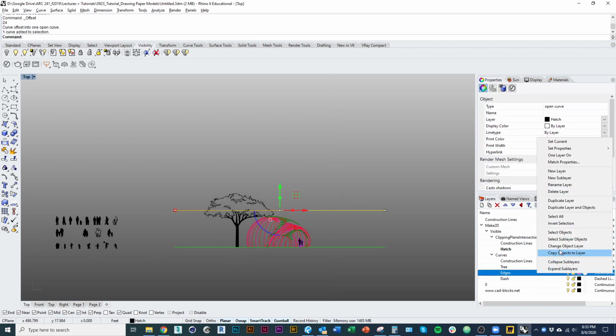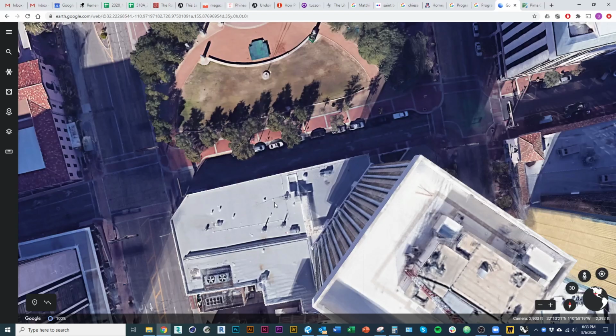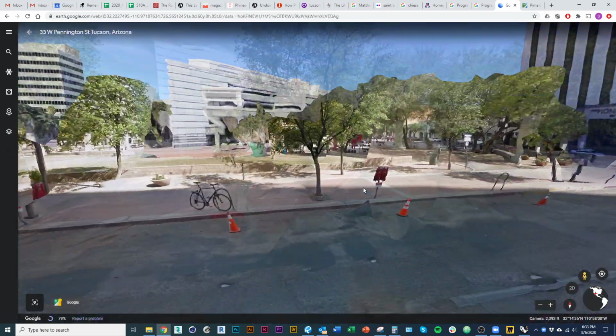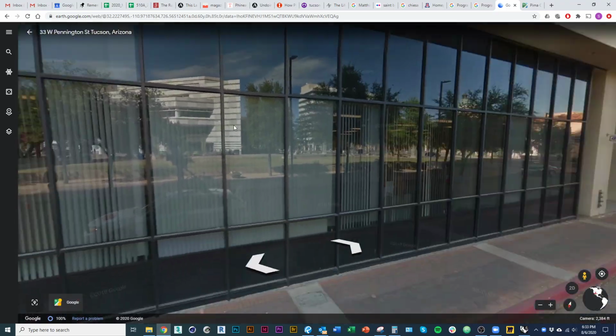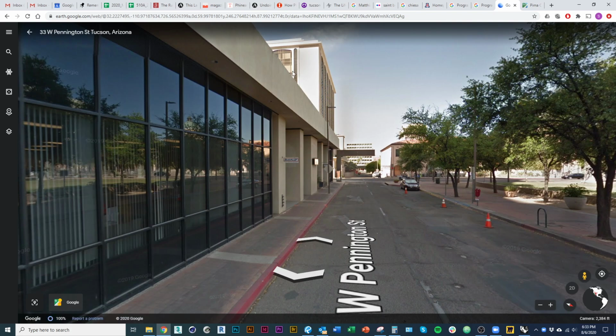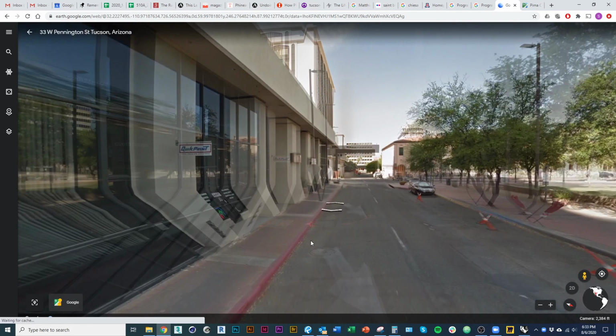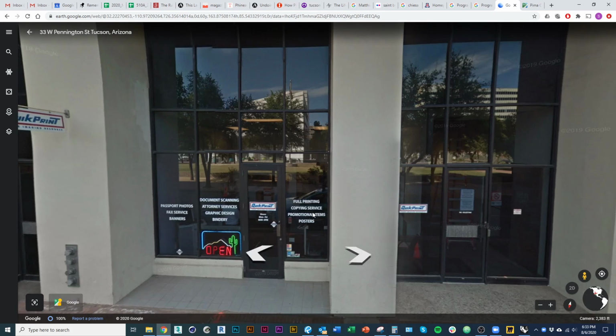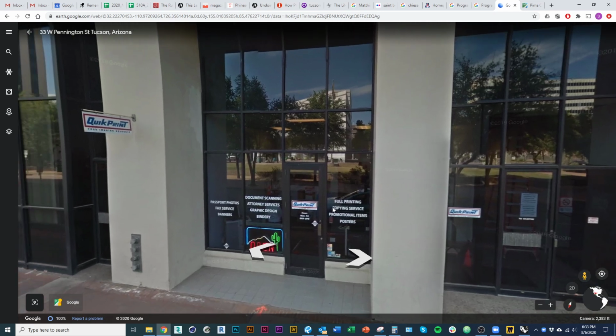And I'm going to change back onto a lighter line right here. And then I would actually just use information that I can get from my street view to look at this building. So we know that that edge is about 24 feet. And looking at the building from this direction, a great thing to reference for the heights of things is going to be our doorways, right? Because most of the time they're actually sized to code. So for example, the commercial code for a doorway is 7 feet, and this is almost certainly that size. So I can kind of guess that